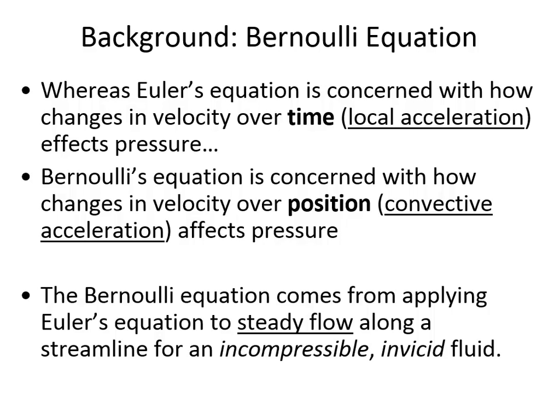That gives you a sense of some of the limitations, and we'll come back to that again. As we work examples and as we get deeper into the concepts, I'll remind you of the limitations, and in fact, in a future quiz, I may ask you to rehearse what the limitations to Bernoulli's equation are, and you'd say it is for steady flow along a streamline for an inviscid fluid that is incompressible. Those are the 4 limitations I'd want you to be able to rehearse back almost as though they were memorized.